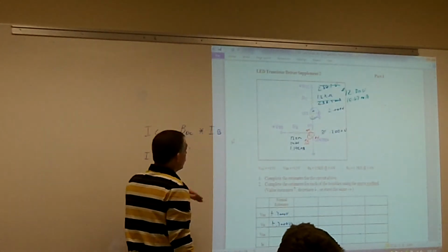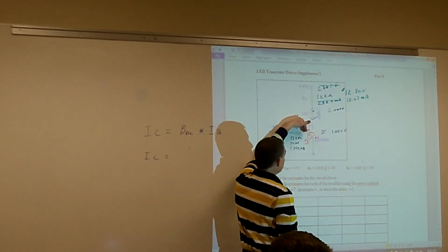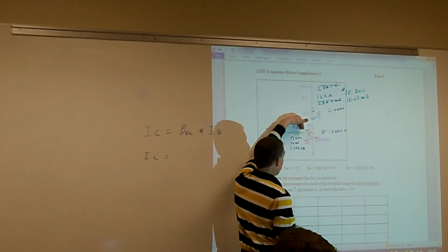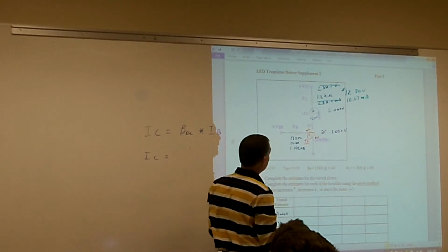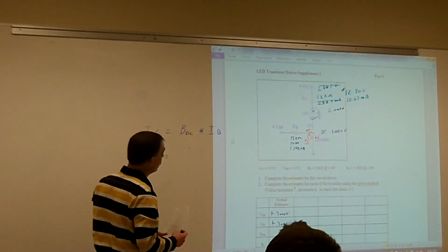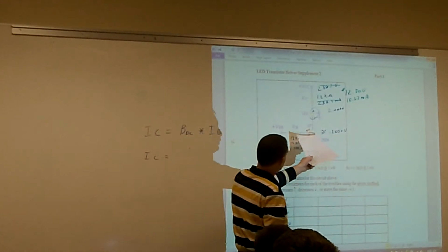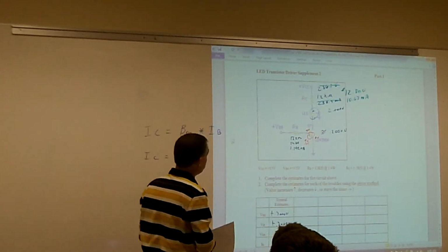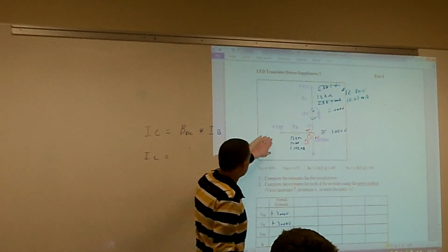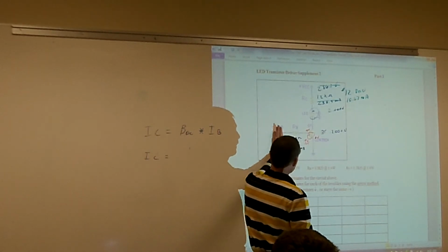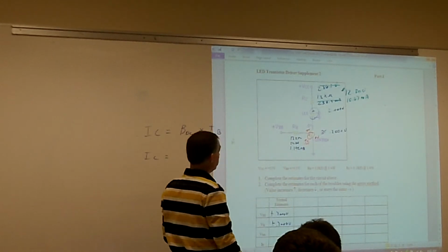That's the other thing. So when we're calculating these things out, we still just calculate them out to make sure that we are truly getting a lot more gain than what we're really capable of for our collector voltage there to maintain that saturation. So we really want to drive that transistor really hard to get that LED to fully turn on. Or if I remove the base and tied it to ground, it would fully turn off, and then it would turn off that LED.